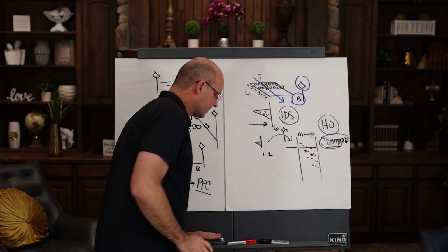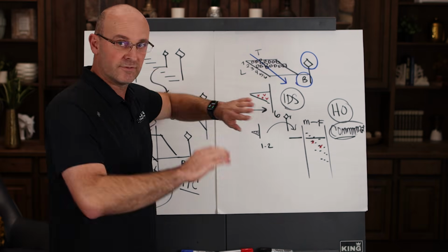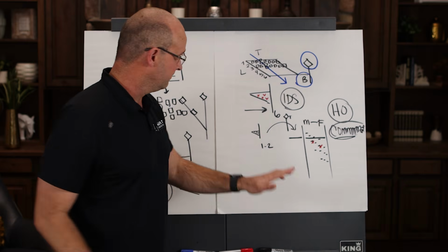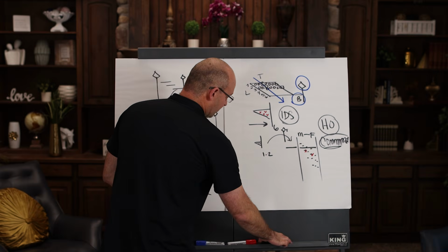Now, we cannot say we're going to do a pull plan, then the production plan, and then create the look ahead plan from scratch and create the weekly work plan from scratch. You cannot do that. These are filtered, not created. What will happen here is a part of your weekly work plan in that weekly meeting.